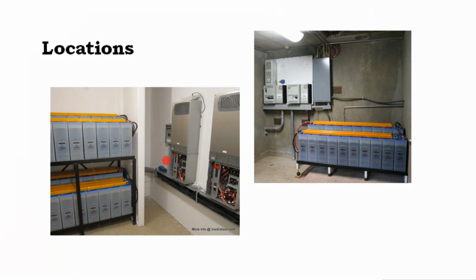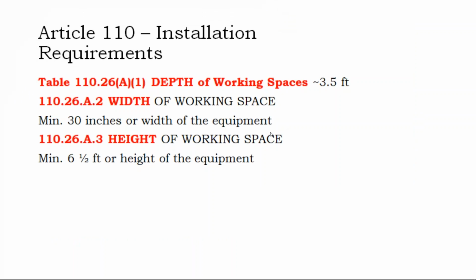And so this space is almost good. If this were a sealed battery that did not require any maintenance, there would be nothing wrong with this room layout. But because you have to maintain that back, this whole layout might have been a little bit better if they had just put a little bit of a window here. Although I guess really accessing these would be hard. Maybe a pull-out tray where you can pull the batteries out, assuming you have enough slack in your battery cables to do so, which is what they do with forklift batteries. They put them on little trays that can come out from the underside of the forklift.